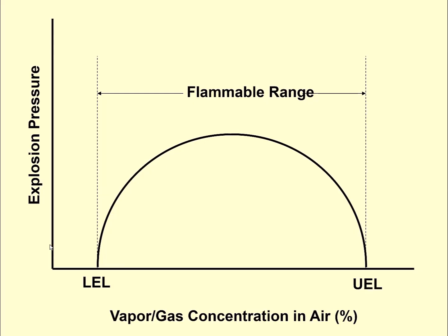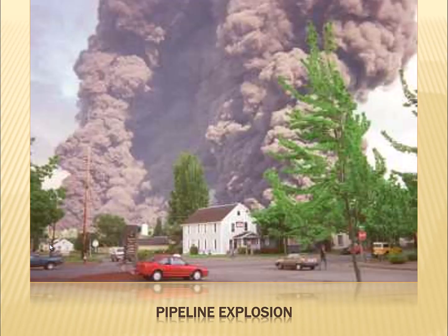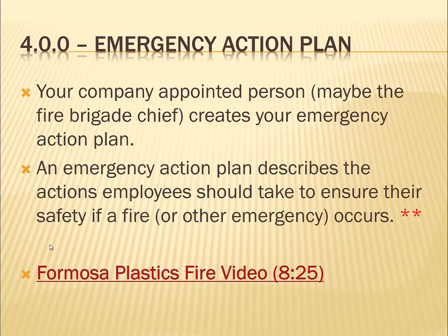Okay, so we don't work anywhere in the range between the lower explosive limit and the upper explosive limit, and OSHA won't let us work above it either. So we can only work below it, but well below it, at 1/10 of whatever that space is between the vertical line on this graph and that edge at the LEL. We have to work at 1/10 of that. And so we test that with meters, and that's what we have to work below. Okay, so we don't end up with something like this.